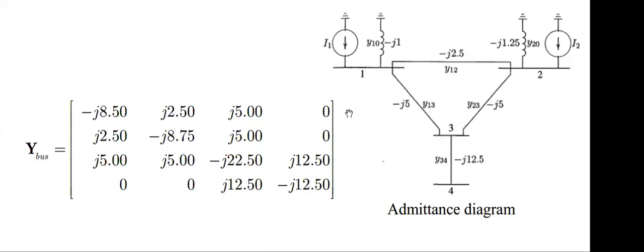So this is the admittance diagram idea. So I think you have got the idea clear of what the generalized admittance matrix coefficient is, and how we can generate the regular Y bus from the reactance diagram. We have started from the reactance diagram, right? Or admittance diagram, whatever you want to say. The modified admittance diagram, you can say. Reactance diagram, then we have generated the admittance diagram.